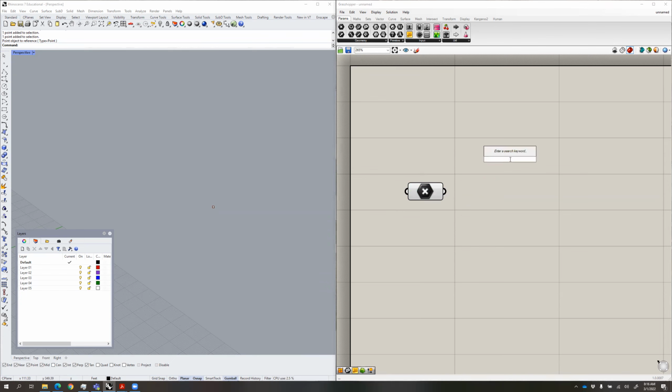So there is a component in Grasshopper called Deconstruct. So I'm going to type in Deconstruct, and you see right here, there's this thing called Deconstruct, a point into its component parts. So I click on that, and then brings up this thing here. So Grasshopper is a visual programming interface, which means you just basically take one component and you connect it to the next one from a left to right orientation. It always moves from left to right, never from the other direction. So that's one way to keep your head straight, is that data always moves in the right direction.